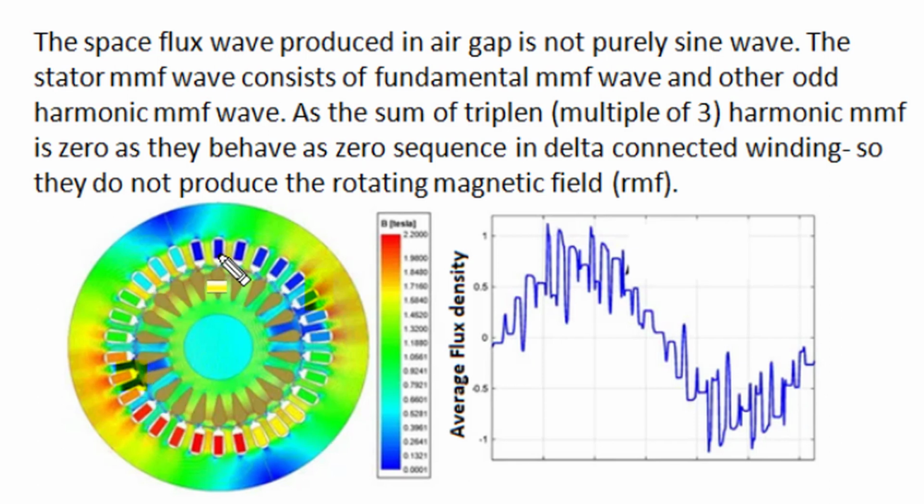And in such a non-sinusoidal wave, at the mid position of maximum flux density, there is a little dip in flux density magnitude, and the flux distribution is not a gentle, smooth sinusoidal behavior, but has certain non-sinusoidal irregularity at peak positions. Similarly, at zero-cross positions, there is some non-sinusoidal behavior in the flux wave distribution.